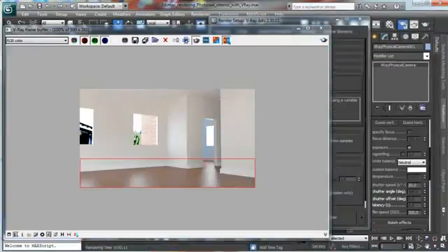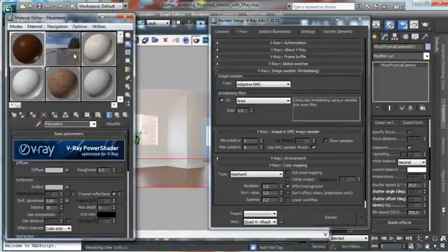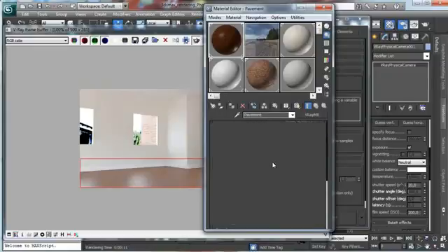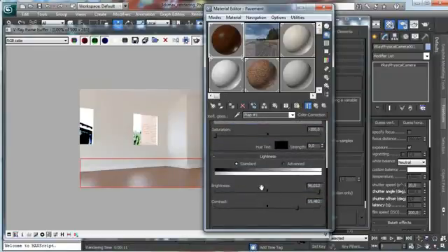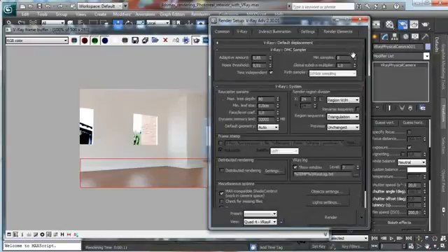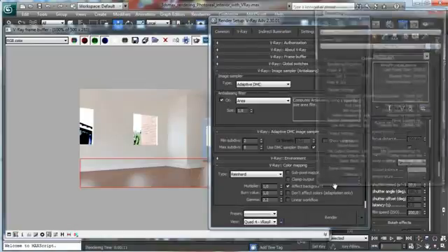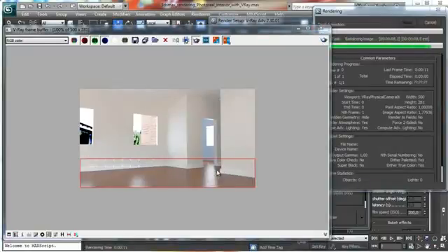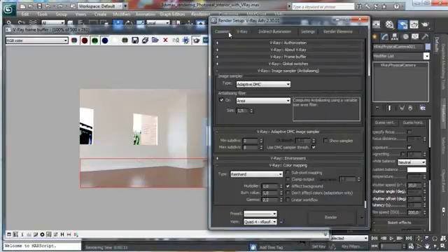Okay, it seems maybe just a little bit too much, so we can go. The things we can do is one is go in there in the reflection glossiness and change a little bit the parameter to something like that, and the second one we can see with a better quality using there a higher parameter. So for example, we can see what happens if we have 32 and 4 for the global illumination, the global subdivision. Let's see again, it starts to be a little bit better.